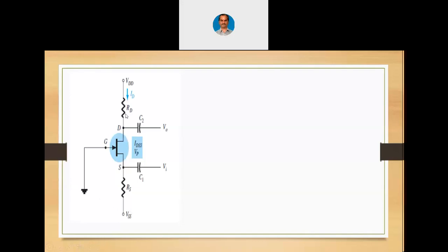And we will have two resistors here, one for the biasing of the drain to gate loop and one for the biasing of the source to gate loop, because the gate is going to be grounded. You can simply visualize one power supply here and the ground here. Similarly, you can visualize one power supply here and the ground here. Anyhow, between drain and source the current is going to flow. Electrons are going to move from source to drain, and the conventional current direction is from drain to source.